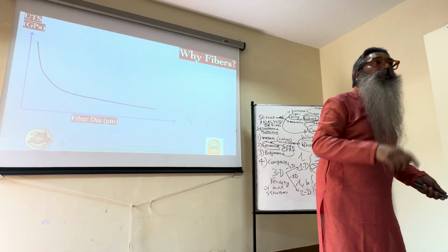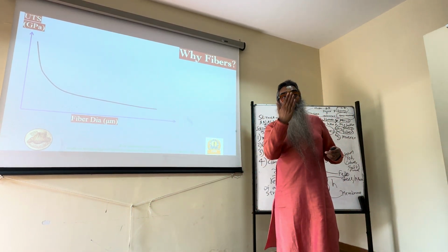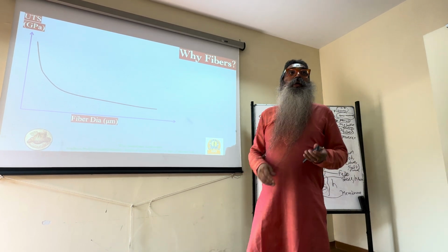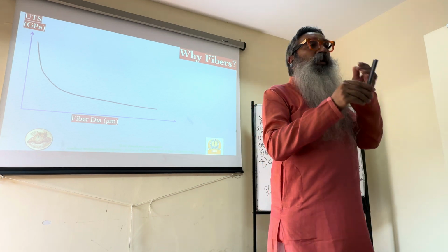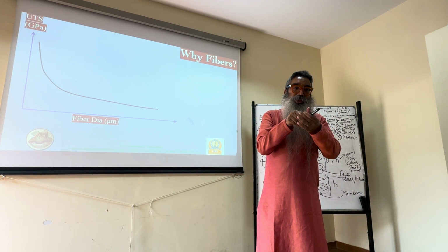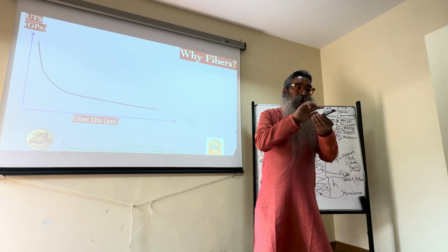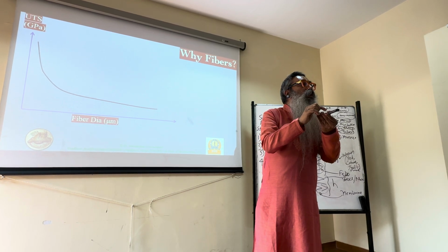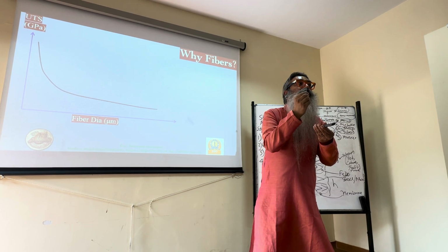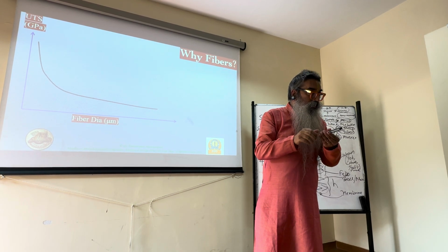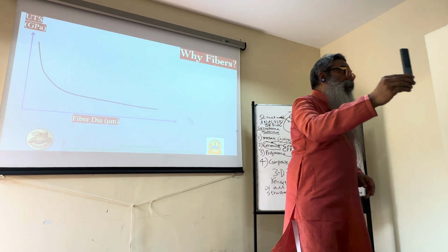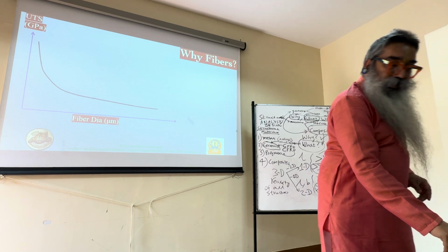And what both of you said actually tallies with that: the manufacturing defects that you talked about, the cracks that you talked about. In particular, what we are talking about is surface level cracks. During the manufacturing and or handling, there can be some small micro cracks that occur, and that becomes the initiation. Exactly, before it's even put on the UTM machine, right?